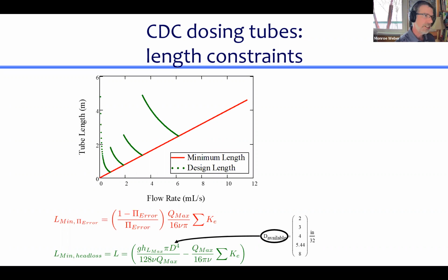Okay, how about we just change the question? If I have variable flow that I can adjust through a tube, and I'm measuring the pressure drop across that tube, if I increase the flow and the pressure drop across that tube then increases, I could reduce the head loss in that tube again by cutting it shorter.